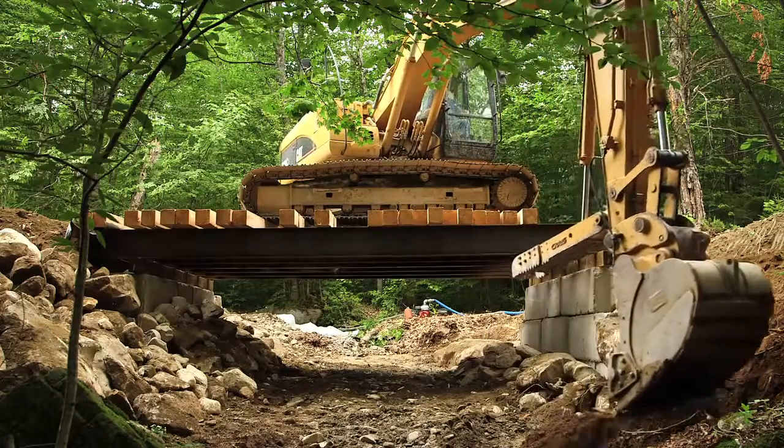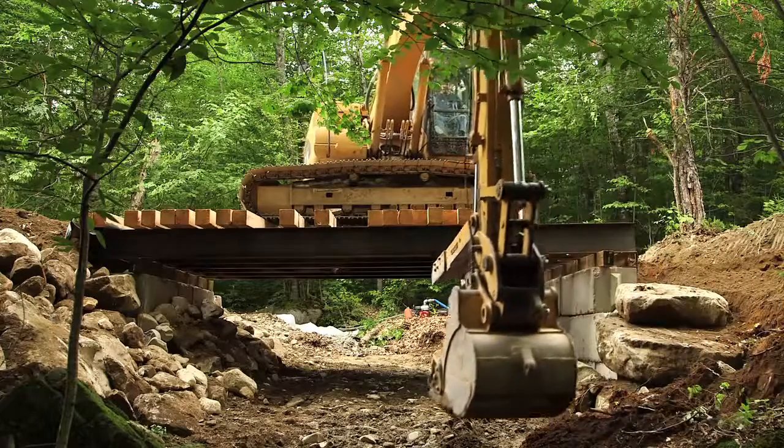We have a lifespan for our practices. In this particular practice, I think it was either aquatic organism passage or stream crossings, had the same effect. And both of those, when we have bridges or culverts, we have a 25-year lifespan. Certainly the 25 years here, if anything, all they have to do is replace the deck. The abutments and the steel girders, they should be here. There's no reason they shouldn't be here 50 or 100 years from now.